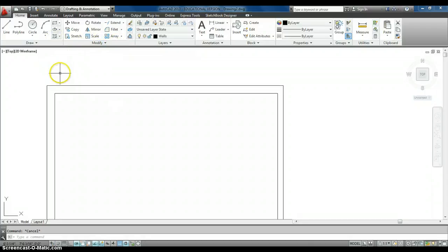So once again, I'm going to go ahead and offset. And I'm actually going to go half of that, 6 feet. Actually, you know what? I have to offset in the middle of my wall. So my wall is actually 15 feet. So I want my window to be centered here. So instead of offsetting 6 feet, I have to offset half of 15 feet, which is 7 feet 6 inches. So I want it to be in the center. And remember, I'm dimensioning everything by the center here.